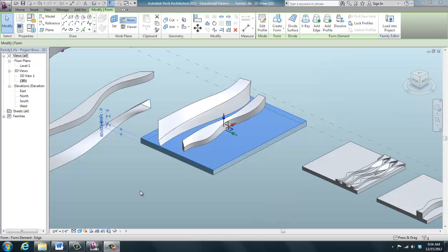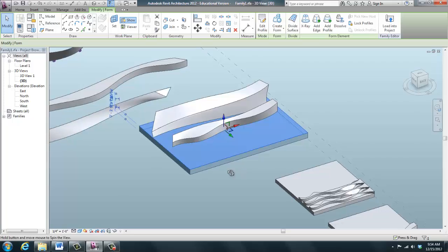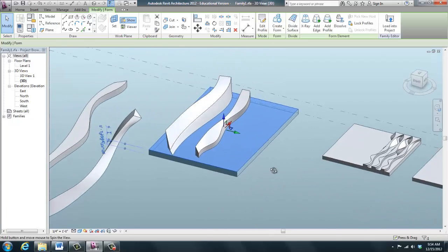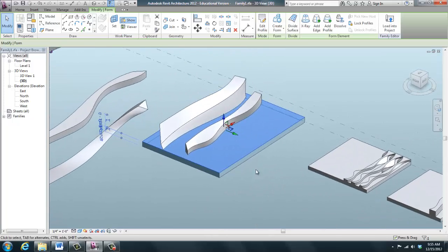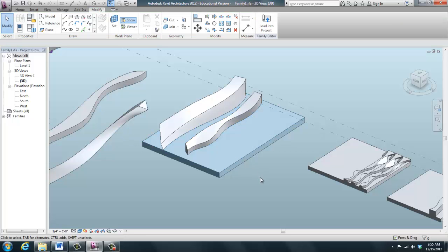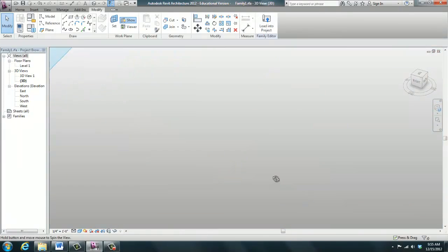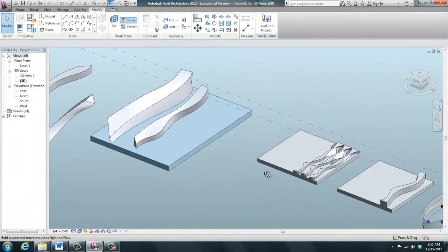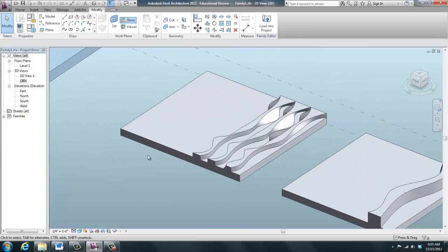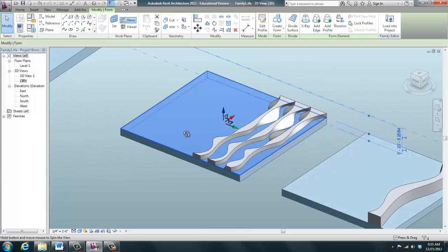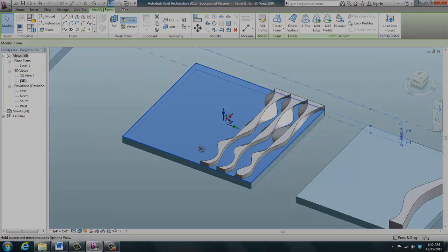When you're zoomed into a view like this, if you select a surface and then orbit using your shift key held down and your wheel of your mouse, you'll have a little more control over the view in comparison to not having anything selected and trying to orbit here. It's not as easy to focus in on that one element that you can orbit around.